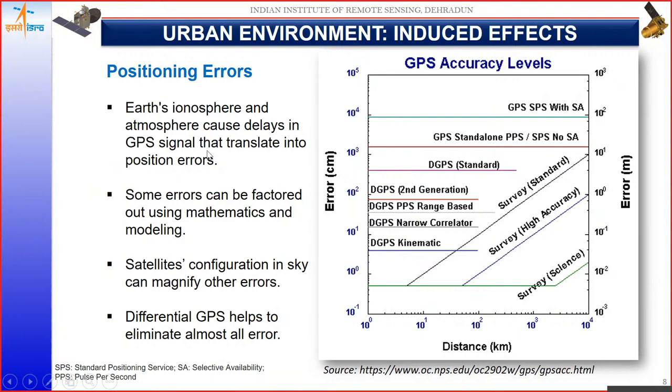So this kind of position error needs correction. Some errors also arise in the post-processing stage, and for several reasons such errors either come into the picture or are corrected. Then we got the arrival of DGPS, the Differential Global Positioning System, or DGNSS, which has helped us minimize these kinds of errors and achieve high quality control points or data